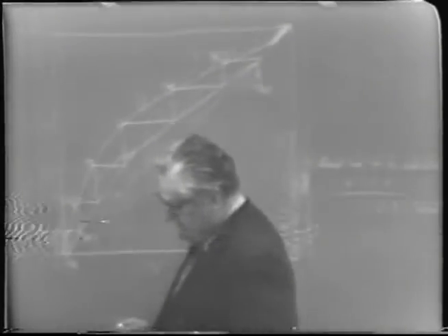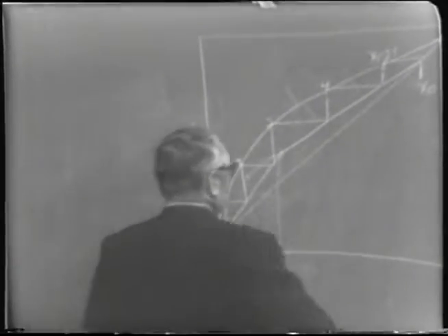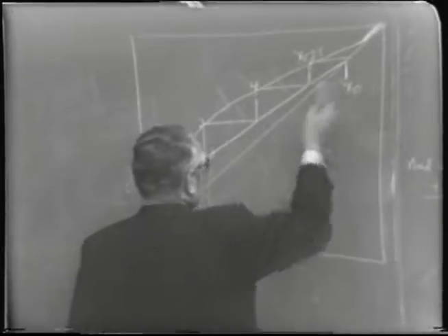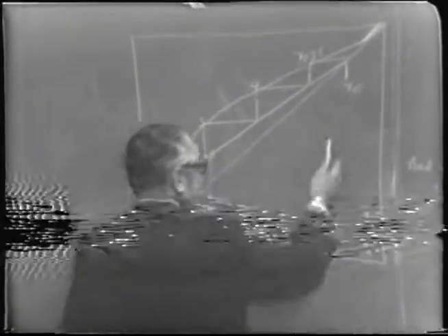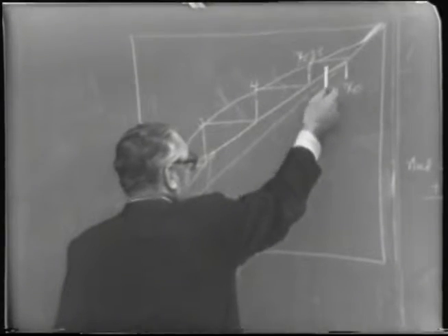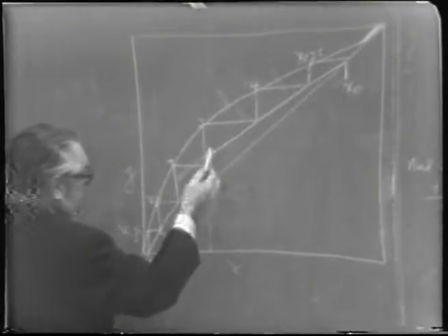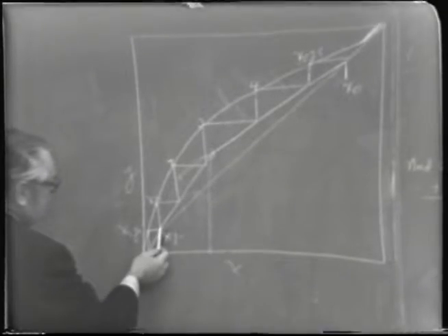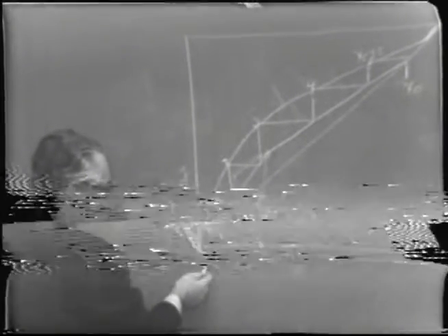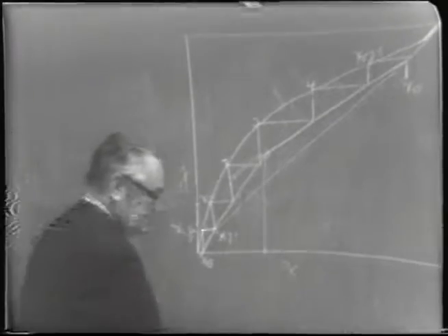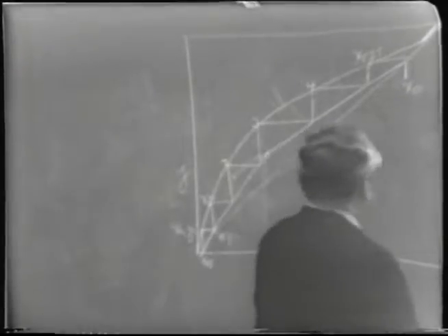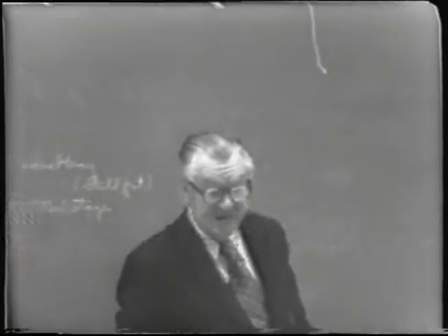And of course, sometimes it's equally correct to start the steps from the top and go down the other way. And in that case, if I had drawn it in a comparable fashion, this last step here would have gone down slightly below x sub B, so it's showing again that the 5th real stage was slightly more than required.